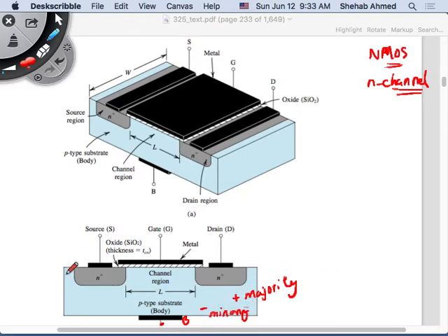And then I grow some N-type material on this substrate. I grow that here, right? And then I add an insulator, so I put some silicon oxide material here. This white material here is a silicon oxide. It's an insulating material that you're able to deposit on the device structure that you've created.